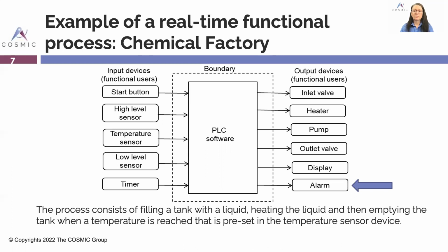If the PLC software is informed that an error is detected, it starts the audible alarm and displays a message to the operator showing the devices concerned, could be more than one. If an operator receives such an error message, then it is dealt with manually outside the software system. The polling frequency is determined by a signal or ticks from the clock in the timer.